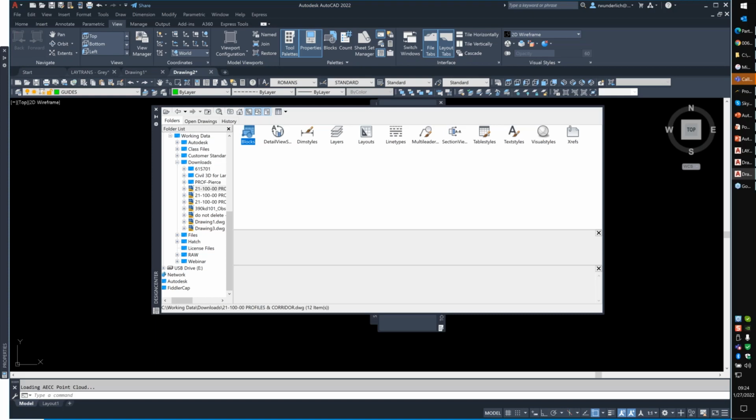Kind of, Darvin. We're going to talk more about that a little later. What you're going to have to go find is that there are Lisp routines and things like that out there on the web that you can use to get a dump of things like that. I have a Lisp routine where I can dump all of my layers and their properties into an Excel spreadsheet.